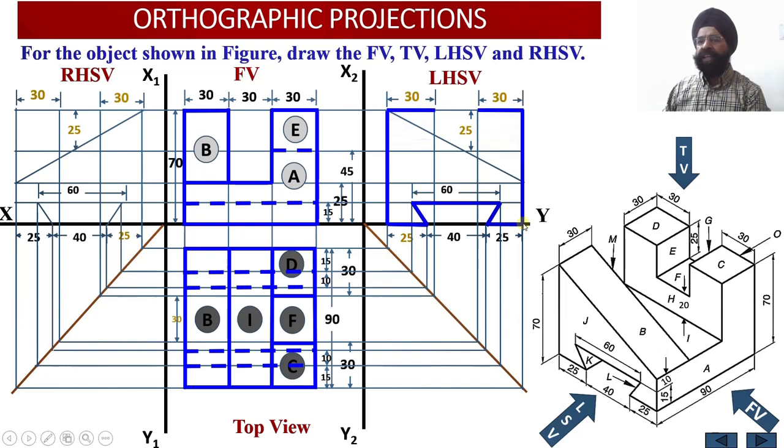Then when the observer views the solid from the left hand side, one thing we are going to see, because this is a sloping area, please see, this surface is sloping. So this horizontal portion of the web edge over here, which is a vertical web, will be visible to the observer. Similarly, this portion is visible to the observer. Now please check, here we have a rectangular slot having a depth equal to 30 millimeter and height equal to 25 millimeter.